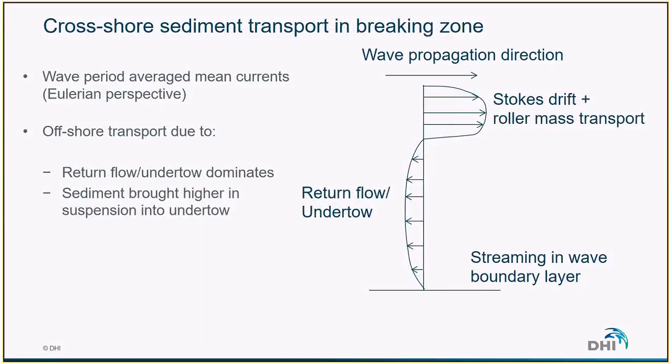When we get into the breaking zone, we have a very strong energy dissipation and turbulence due to the wave breaking. All the mechanisms that we've seen outside the zone are also relevant inside the surf zone, but their significance is small because the energy dissipation in the wave boundary layer is much smaller than the energy dissipation due to breaking.